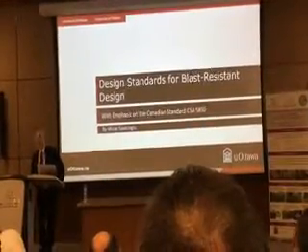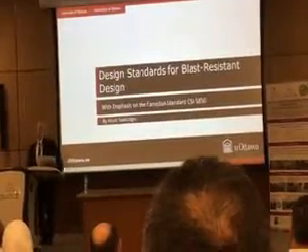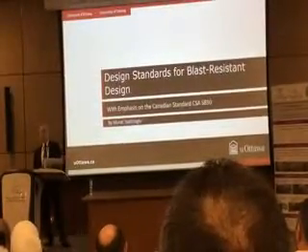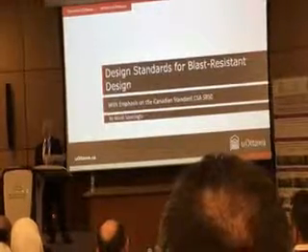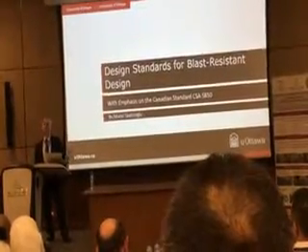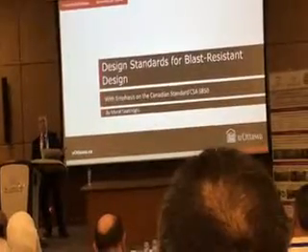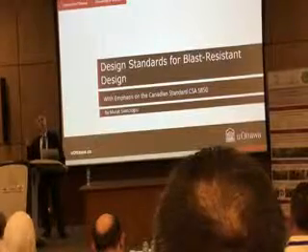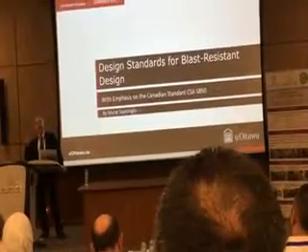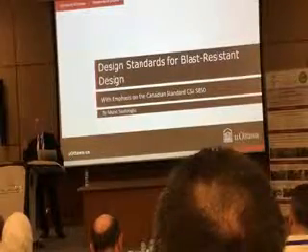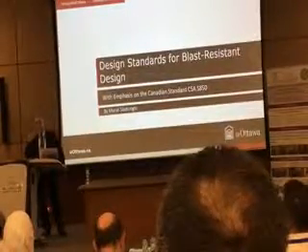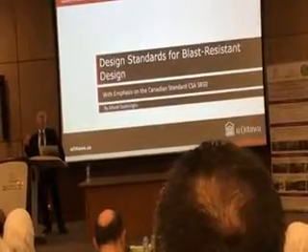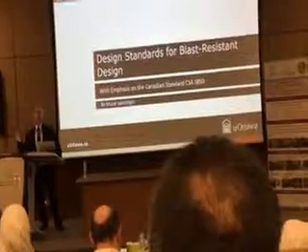Of course, in the equation of motion, you have damping coefficient times velocity, which is the damping effect. Now, damping in structures is very important. If you don't have damping, things will vibrate forever. In earthquake engineering, it's very important. We consider 5% of critical damping. In blast engineering, damping is usually ignored unless you have a computer program that includes that. So, for the simple approach that I have taken, I ignore damping. Why? We're talking about 5 milliseconds. There's not enough time to go through damping, right?